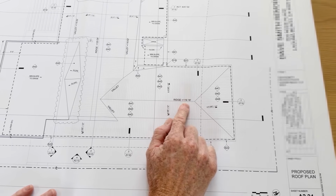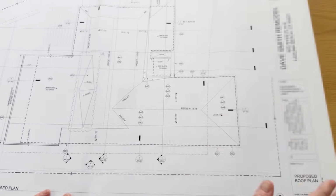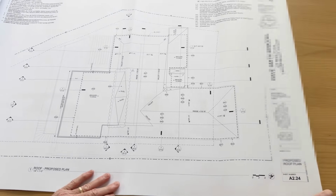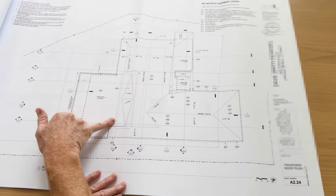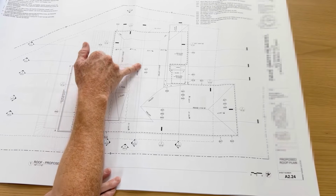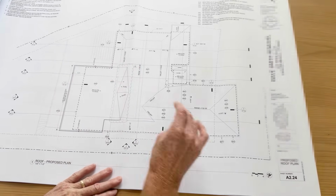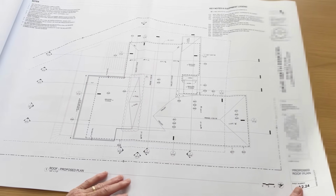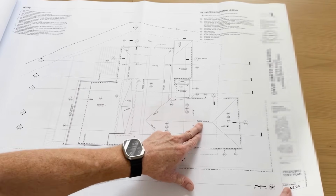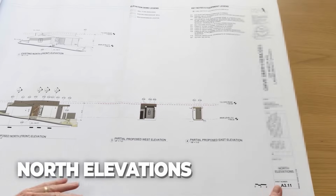So a lot of building and county code requirements don't allow building height to go higher than a certain elevation. And so when we're building and framing buildings and houses, we want to make sure that we're very much paying attention to this. So if we're doing measurements along the way and we find out that we're going to be higher than this, we want to make sure we address it before we install all of our roofing compositions. So again, more abbreviations. Key component here is making sure that we identify and stay in line with those ridge heights.